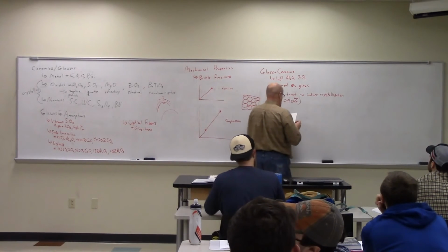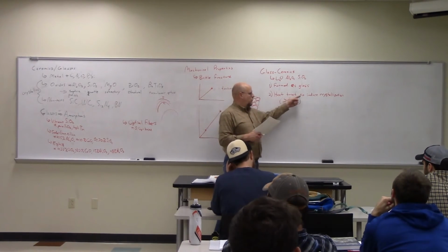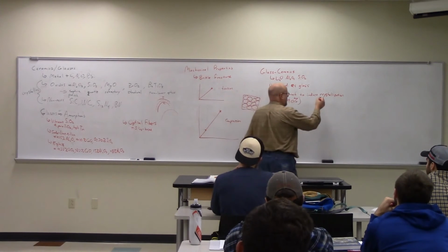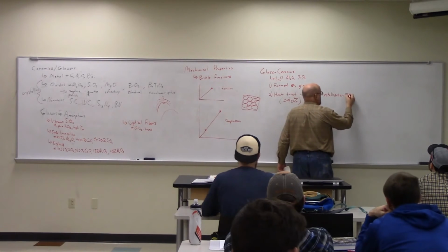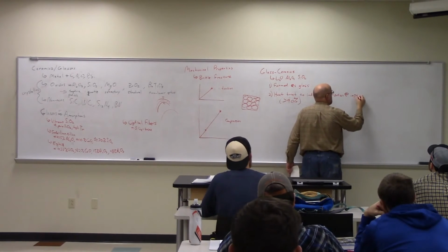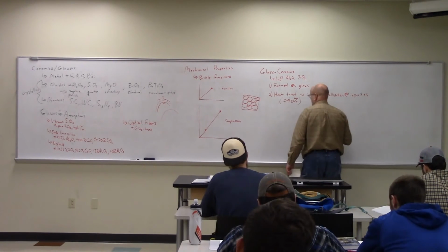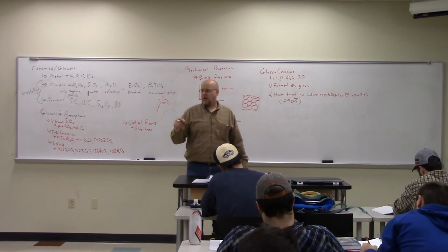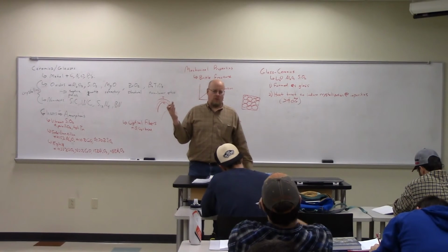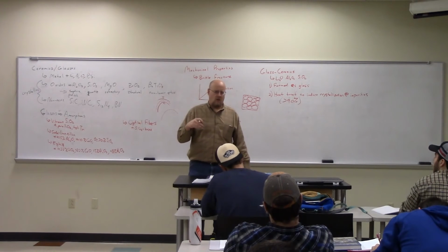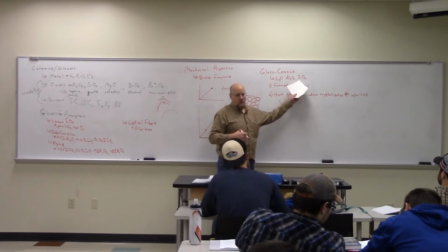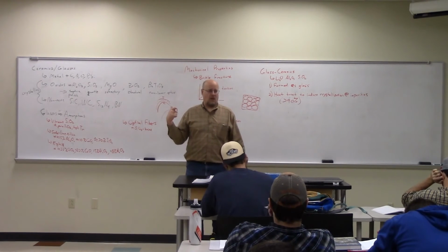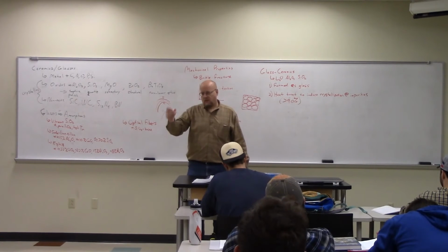Anyway, the way that you induce the crystallization is you dope it with just a little bit of impurity. Crystallization occurs at the impurities. You can imagine you have this big thing of glass, and you sprinkle a very fine powder of titanium dioxide, which is the same stuff that makes white paint white. There's very little of it in terms of the actual composition, but it's enough to serve as a local nucleation site. Again, I'll refer back to heating the cup in the microwave. You've got to get things to nucleate, and then you've got to get them to grow.